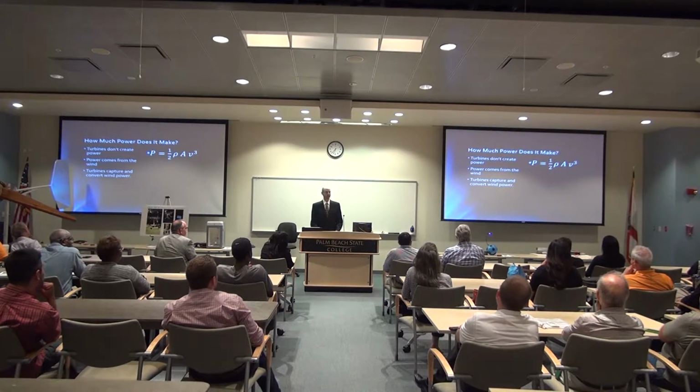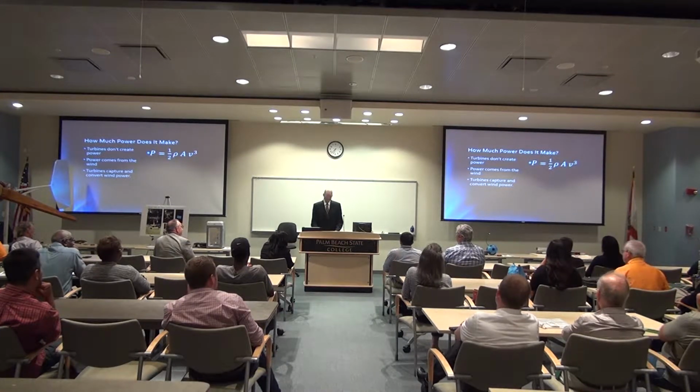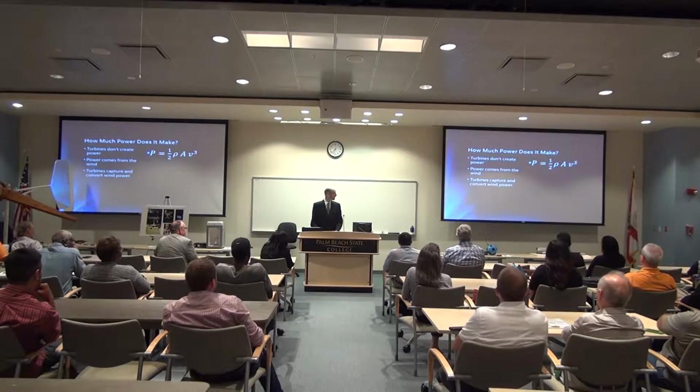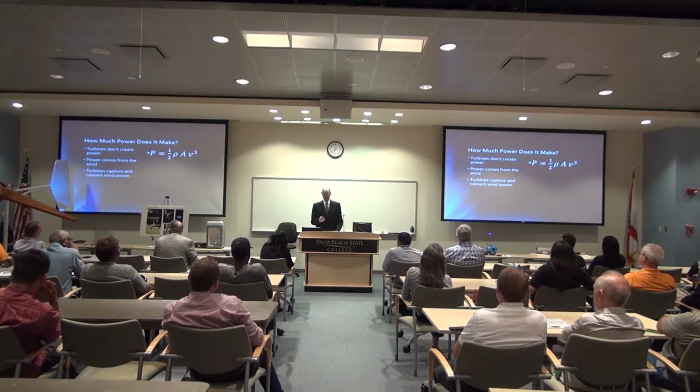Well, the density of air, can we influence that where our turbine is? A little bit, actually. There are some things we can do that'll affect the density. We could say, for example, put the turbine at high altitude. If you were to put this turbine in Denver, Colorado, it would only make about 85% as much power as it would make here in Florida. Also, humidity and barometric pressure will affect the density of the air, but there's not much to do about that. Area, we can definitely affect how much area is intercepted by making a larger rotor on our turbine. And velocity of the wind. Now, I might be a magician, but I can't definitely control the velocity of the wind.